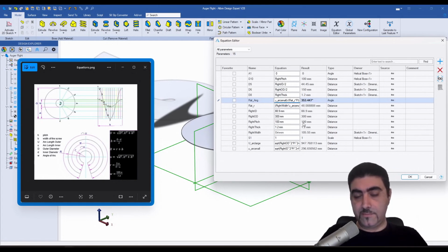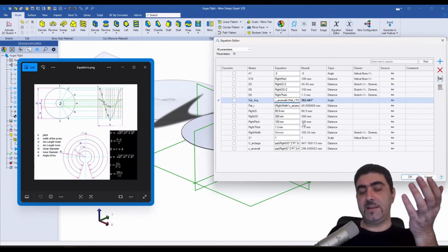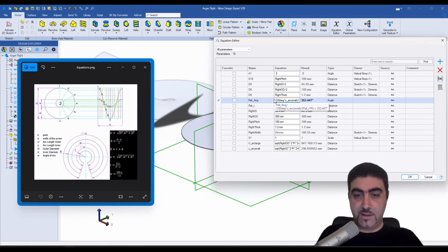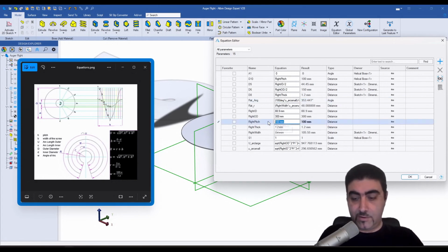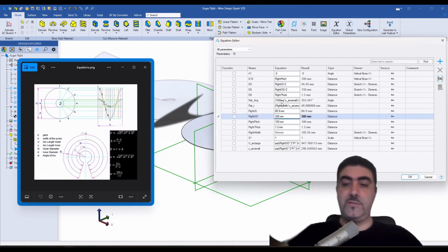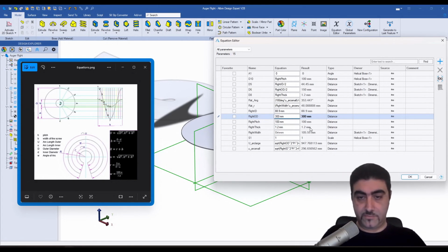U arc small is a distance, flat r is a distance, and pi is a unitless number. So it was dividing and getting a unitless number, and it didn't know what to do with it in the angle type. So as soon as I said 180 deg, which is the definition for degrees, it worked. And now we don't get these wild shifts anymore. Yeah, there you go. That is the correct angle, 353 degrees, and so on and so forth.